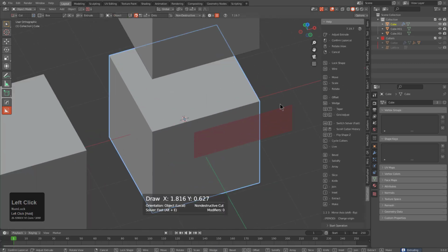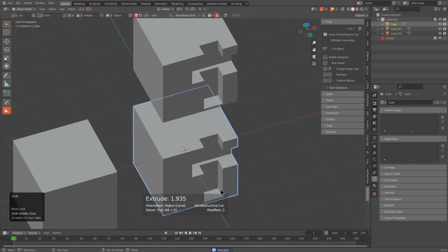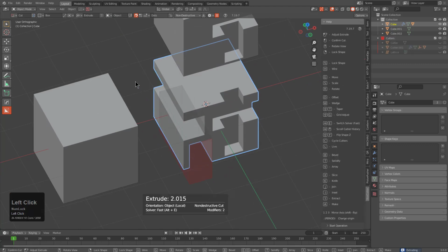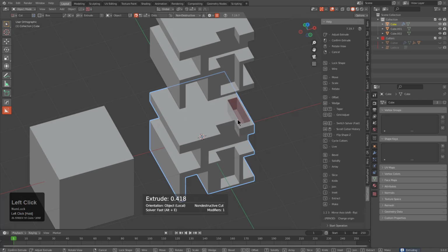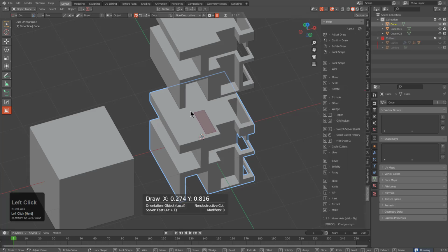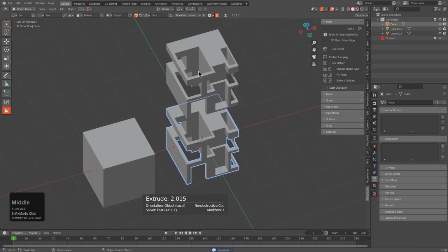So let us just perform a cut, let us perform another cut, and click Apply, and we see that now it actually goes over to the multi-use object without having to break the data. So this is a big improvement. I did another video where I went in a little bit more depth as far as what this means to Boxcutter as a whole by being able to work with multi-use data, but this is definitely one of those things that anyone keen on their Blender has definitely noticed as an oddity with Boxcutter, and I'm just glad to see that it's finally been resolved and we're able to cut and retain object data shared across multiple objects.